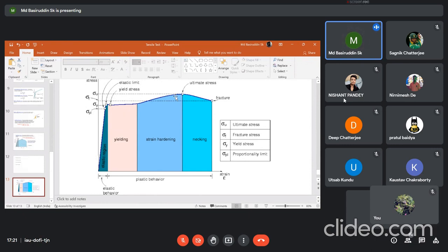Okay. So if n is equal to 1, how will your curve be, because k is constant? So the strain obviously is there. If k is constant, it has the same unit as stress, right? And the strain has no unit, so it will be just multiplied with the k, right? Then how can you get this particular thing if n is equal to 1? Will it show some sort of strain hardening or something?